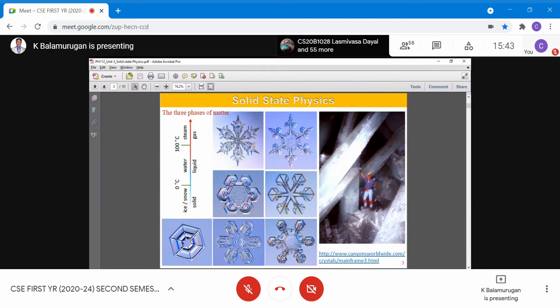You can use quartz crystal. You can cut the quartz crystals in a particular specific direction and thin them down to a specific thickness, etc. And then if you apply some potential to them, they can be used to maintain time. All digital watches have a small cylinder-shaped component that would appear like a capacitor, but it's not actually a capacitor. If you open and see inside, there will be a thin plate of quartz crystal.